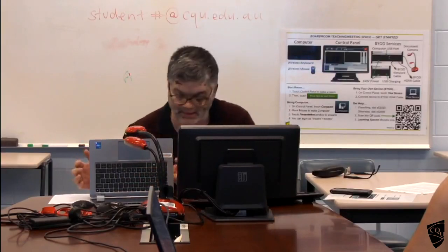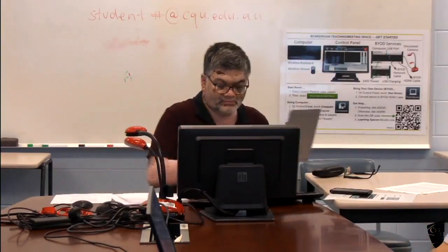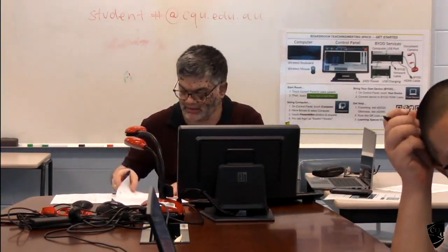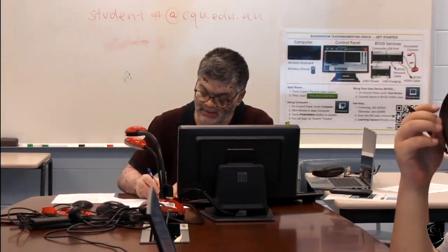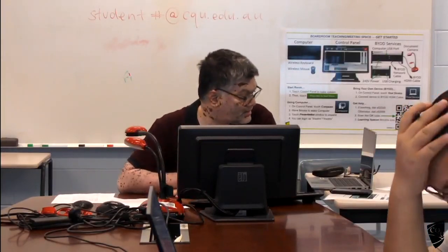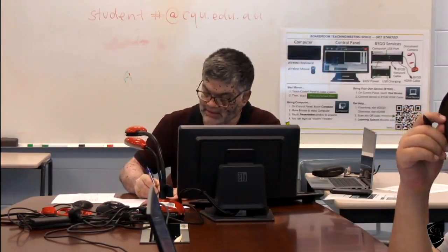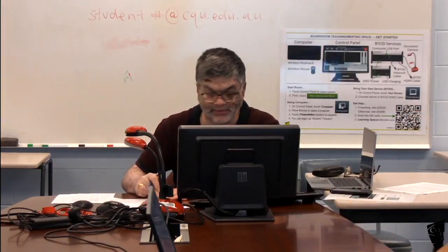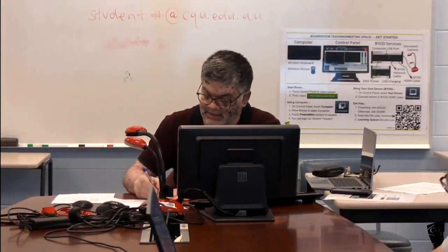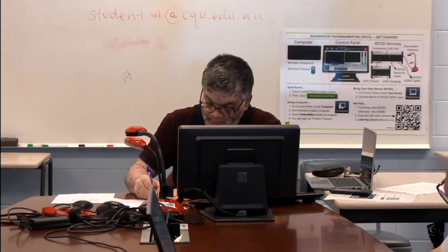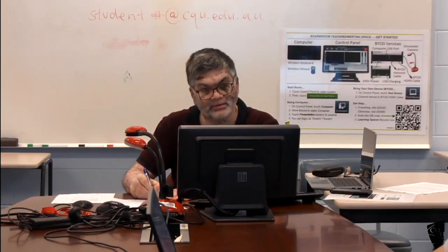So the first one is, so my case, this is the end span. They said exterior negative moment is 0.25. Exterior negative moment. This is the exterior one. This is exterior negative moment 0.25. So you just need to multiply the MO1 by that factor.